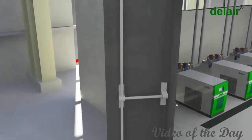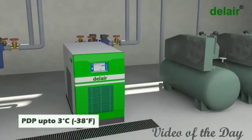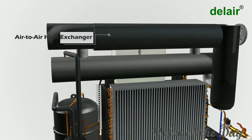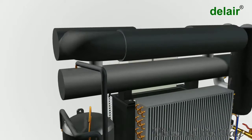Refrigeration dryers are suitable where applications require a pressure dew point up to 3 degrees Celsius. The main components of a refrigeration dryer are a proprietary air-to-air heat exchanger and an air-to-refrigerant heat exchanger. Delair also does a variety of advanced heat exchangers.